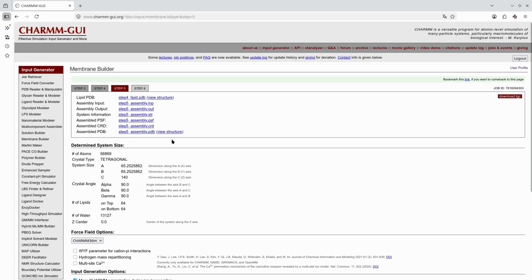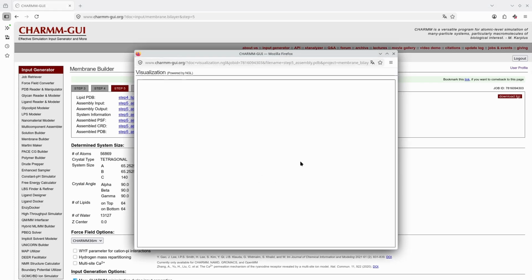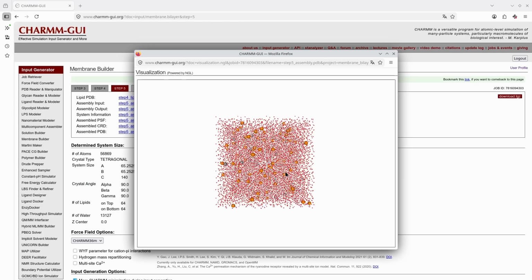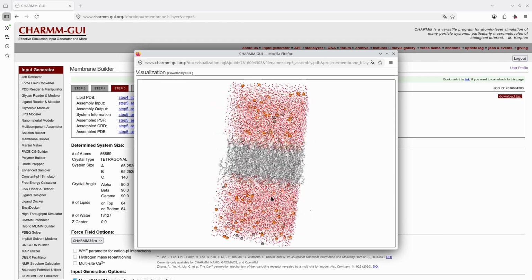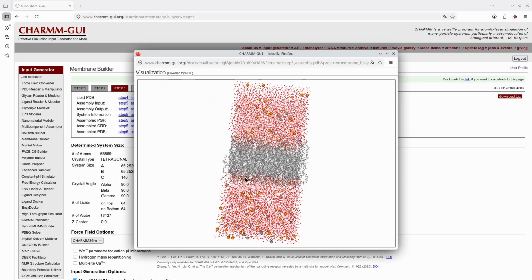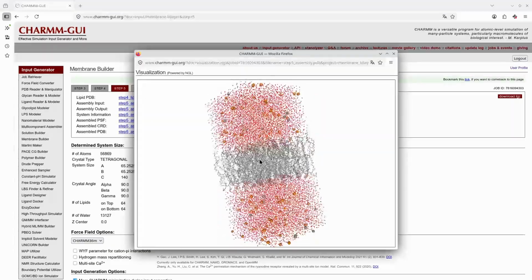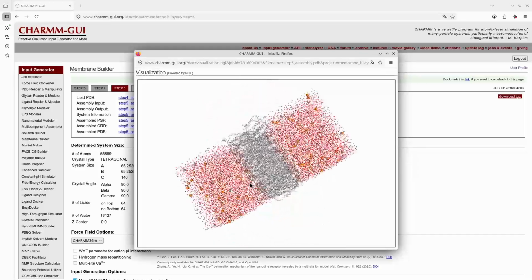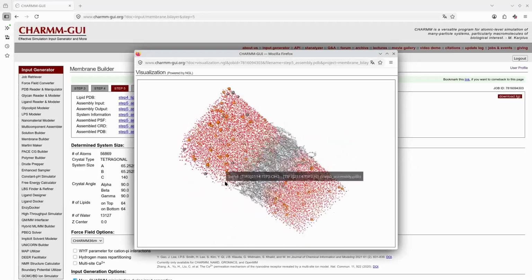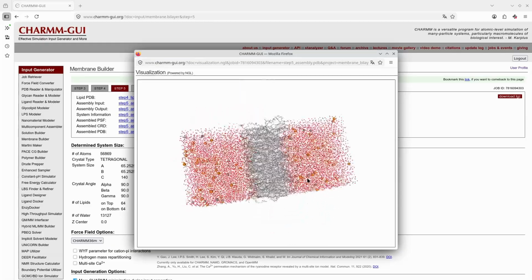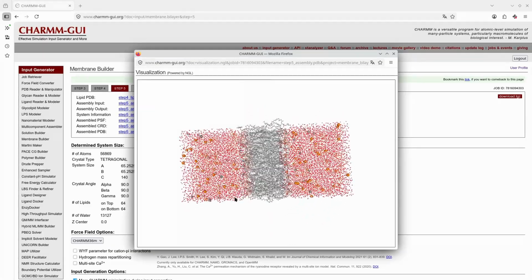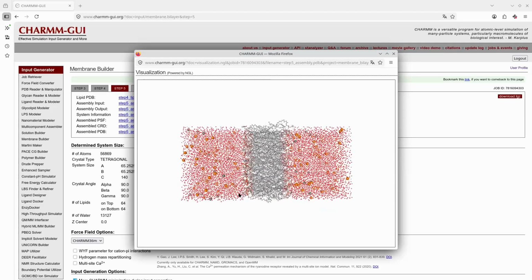Also, there are other force field related options like the NBFIX parameter, if you need to model cation-pi interactions more precisely, but in that case you might also want to switch to the Drude polarizable force field, which requires a different builder. Then hydrogen mass repartitioning is basically where your hydrogen atoms, as far as I know, are fused with heavy atoms, and this is if you want to switch from a 2 femtosecond integrator time step to 4 femtoseconds, which means that your simulations will reach the desired time 2 times faster.